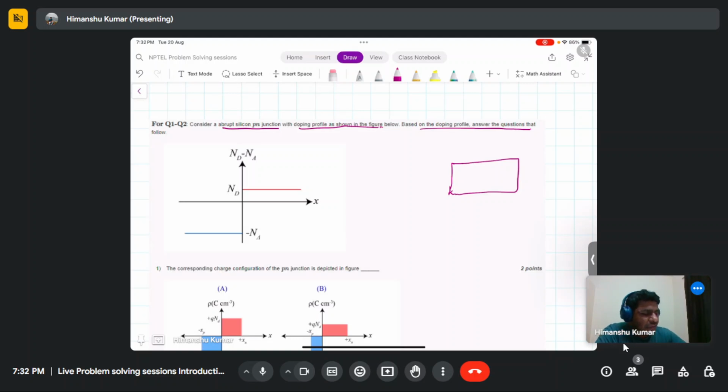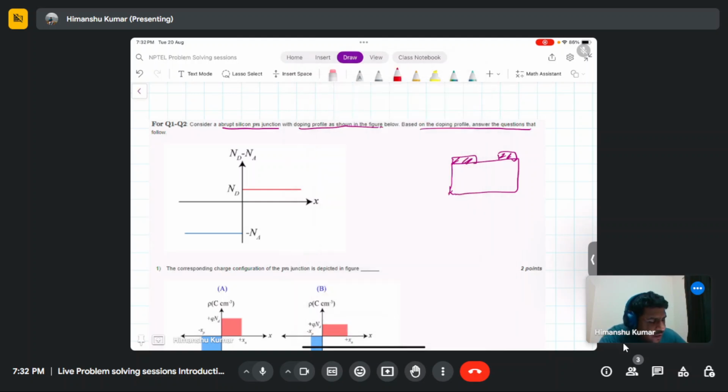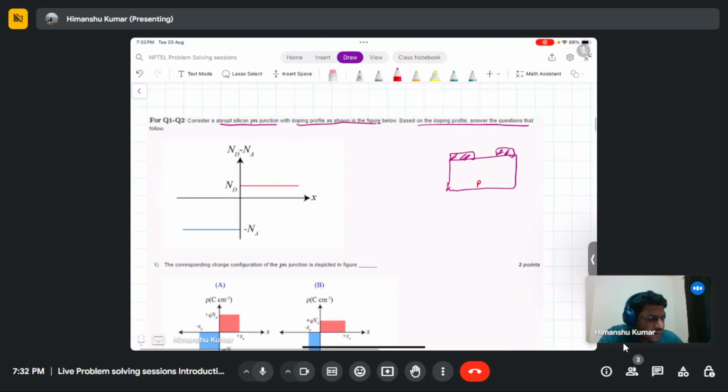When you make a PN junction, basically what you do is you make a region like this, and then you create this window by some photoresist material, and then you do the diffusion here. Initially the starting substrate is your p-type, or whatever the complementary substrate you have. So this already has acceptor type dopants.